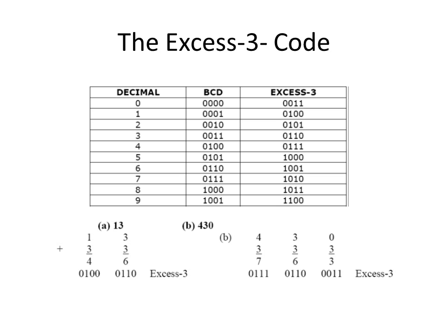For example, 1 in BCD code has 3 added, and 4 is its XS3 code. If it is 3, then 3 is added and it becomes 6. Similarly, 430 is a decimal number. Its XS3 code is represented as 763. So 7 is represented as 0111, 6 is represented as 0110, and 3 is represented as 0011.